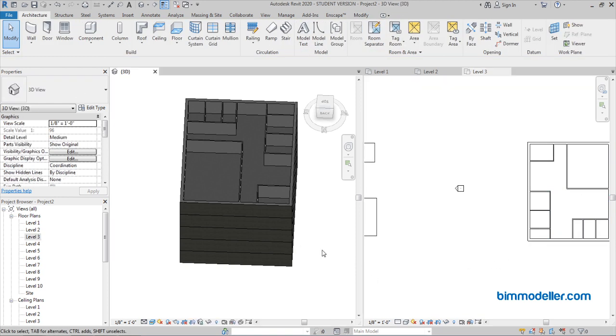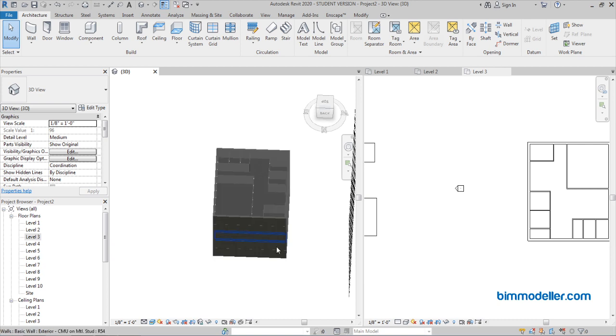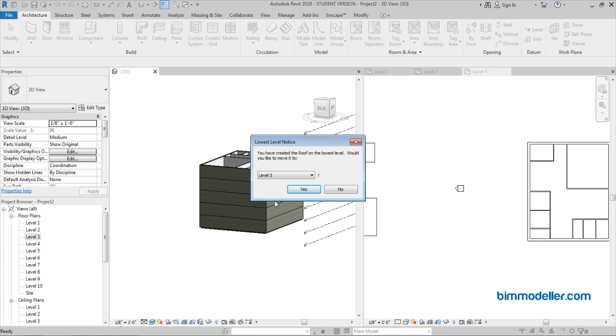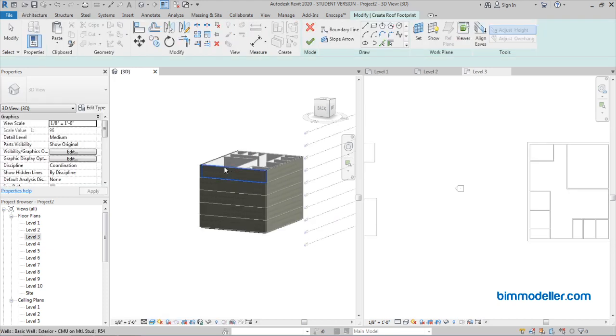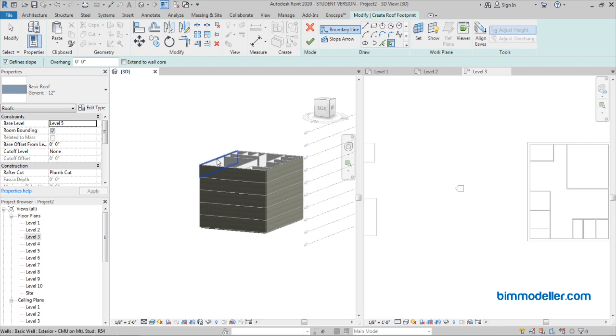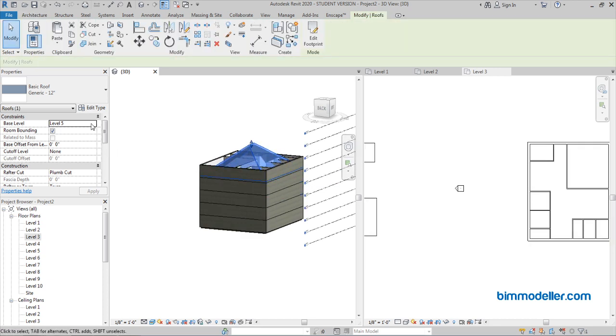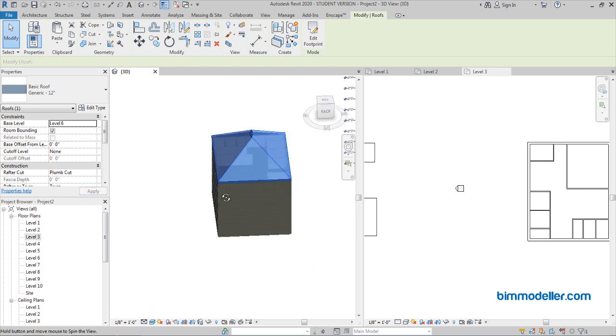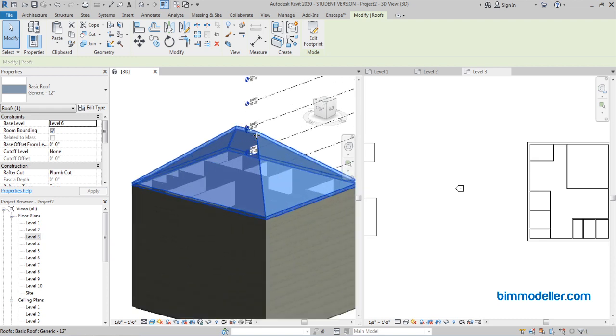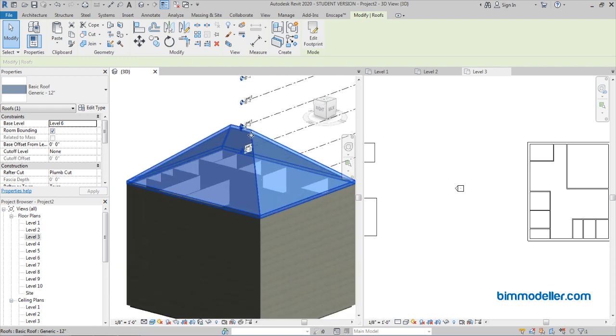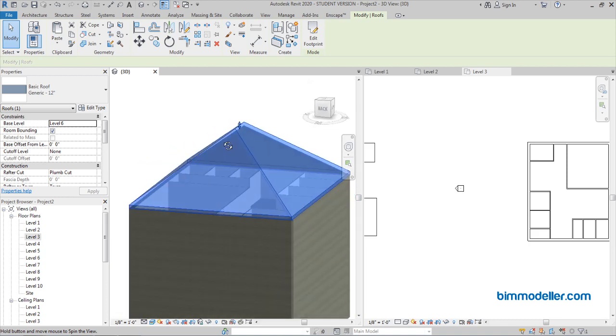Later, if you need your roof to be created, you have a roof plan in this place. We want to create the roof at level 5, I hope, not the 6. Let me check that. And by picking the 4 walls using the tab button and finishing it, it is creating on the 5. Let us make it 6. Since Revit is a parametric tool, you will be able to customize or change the design at any time.